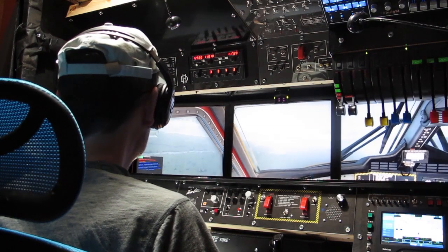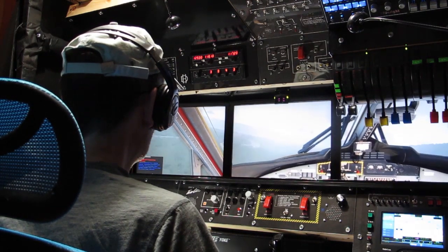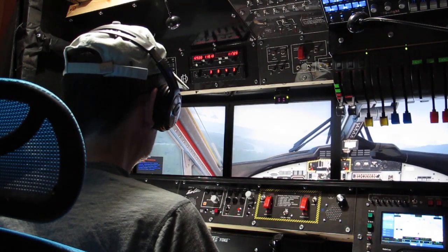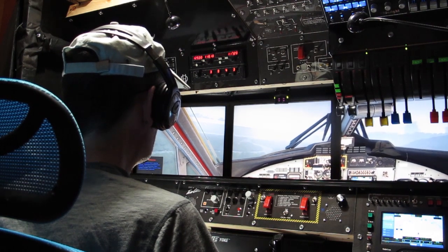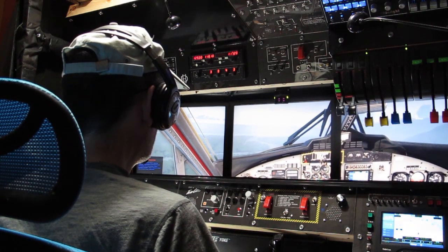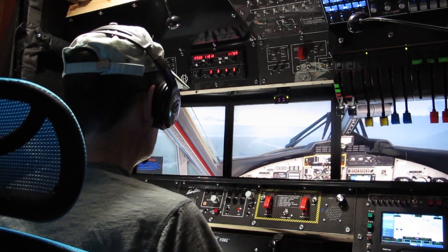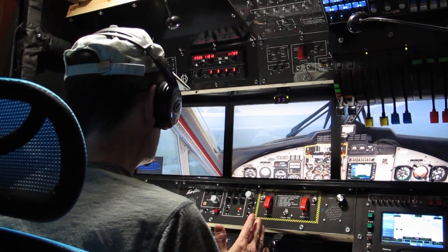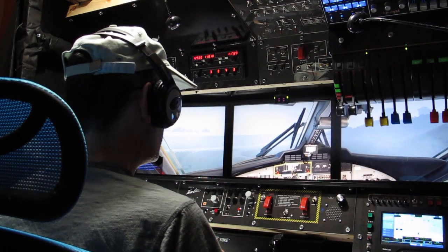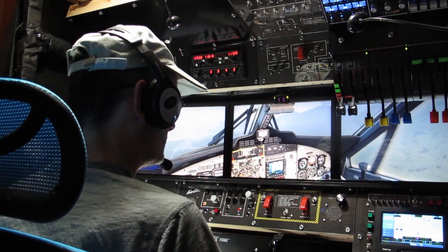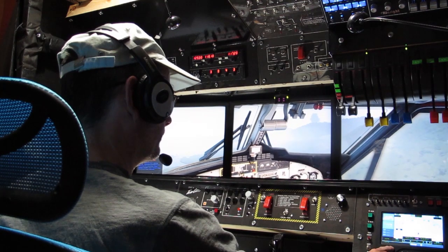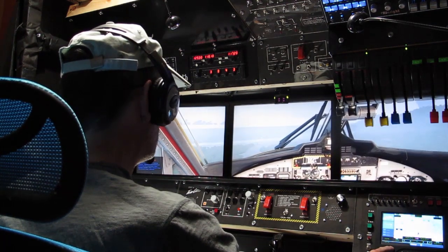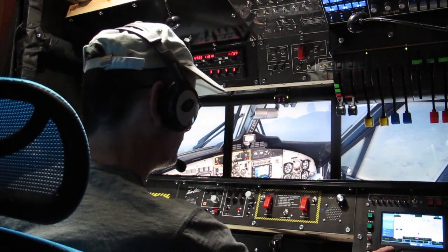So we're at 700 feet. We're going to overfly the airfield threshold on airspeed hold. So it's quite precisely holding an airspeed for us. And we're going to check out the ground speed on the GPS. So we're on heading 290, which is perpendicular.